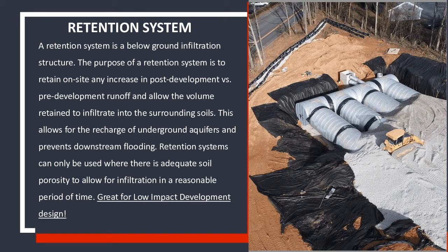One thing I want to mention after reading that is that obviously location is really everything with a retention system. Down here where we are in Georgia, we have a lot of clay soils, so it's really a 50-50 shot as to whether you can infiltrate or whether you can't. And then, we mentioned a reasonable period of time. Typically, that's about 24 hours. You want to see your infiltration within a 24-hour period.